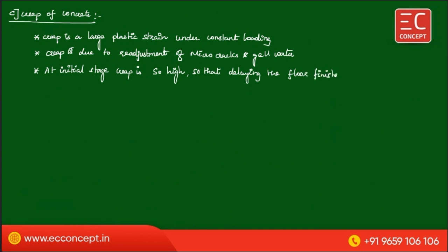This is somewhat application oriented. So delaying the floor finishes at the initial stage, in order to reduce the creep strain.